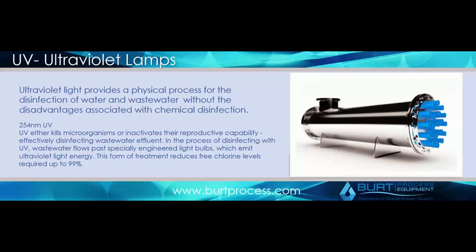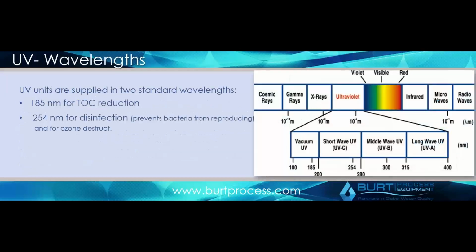One of the downsides of having a resin bed is that your water is now passing through a block of granulated material, and anybody who's ever owned a fish tank knows that if you have a charcoal filter in there, in time it will turn green. It's a very good site for bacteria to grow, even if water is still moving through it. So a UV light is very critical in maintaining that bacteria level within your actual system.